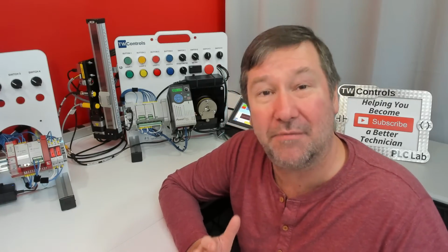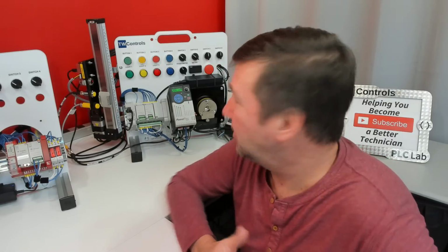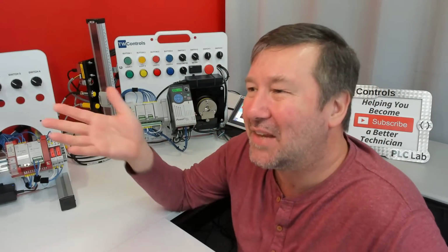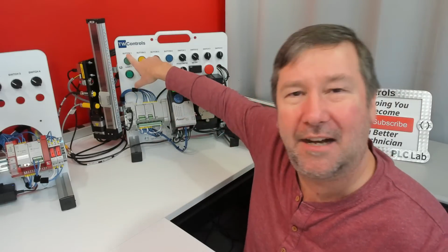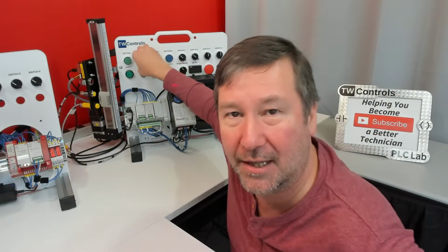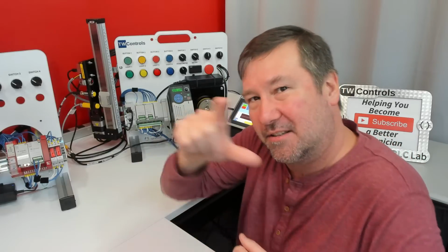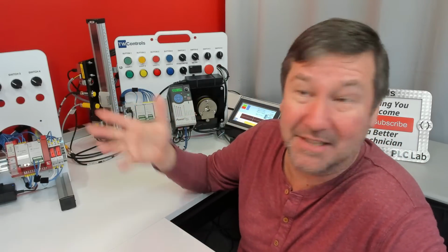Usually it's an input, but it's interesting. Most people do the opposite, because even if you know nothing about PLCs and you call someone and say, hey, the green light won't turn on, I don't even know what program's in this thing, not enough to do anything, apparently. But say the motor won't run, the pump is not pumping. You call the programmer, they're never going to tell you, go look at the pump. No, they're going to say, go check out the gate switch. Go check out the low level. They're going to tell you to go check those inputs, as they're looking through the program trying to figure out which one is not working.